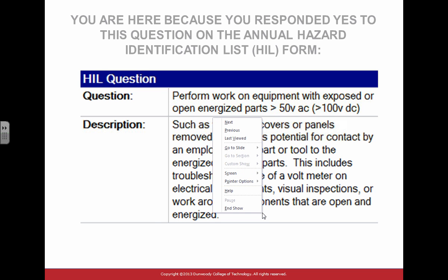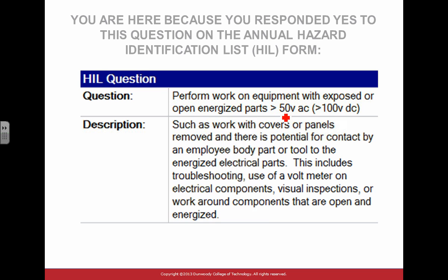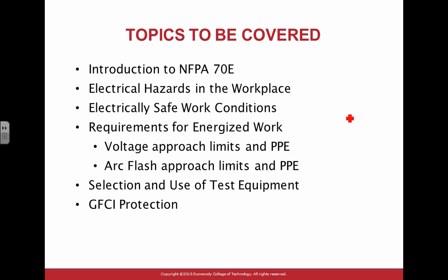So that's your survey. Let me grab my highlighter here. If you work on energized equipment more than, and drop please the DC here, this is wrong. Typically, if you work on anything more than 50 volts AC or DC, it's considered high-voltage energized. I have been told by Tim Coyle, who put it together, that you guys are going to change this. So it's more than 50 volts AC or DC. If you work on it energized, you have to follow rules and regulations based on that. So that's the justification for you being tortured by your friend Chad today.